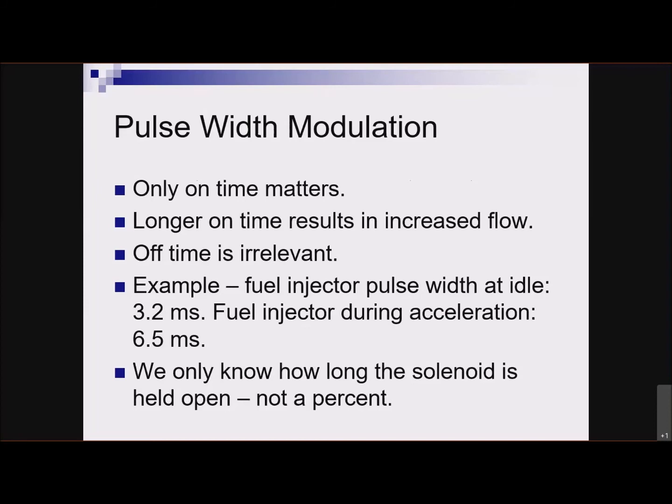How long do we want to open it for? Do we want to open it for 3 milliseconds? Do we want to open it for 4 milliseconds? How long do we want it off? We don't care until the next time it needs to open, which is going to be exactly 2 revolutions later. That's going to be completely dependent on how fast the engine's spinning, right? But our fuel needs are not dependent on just how fast the engine's spinning.